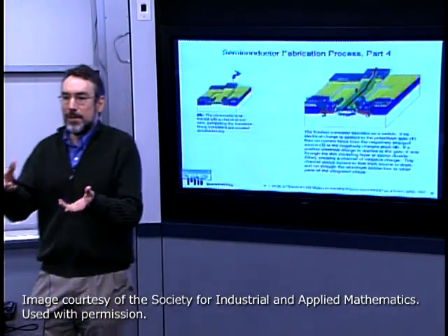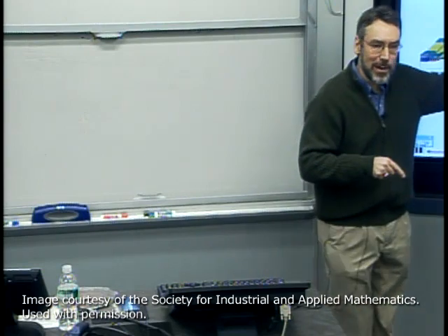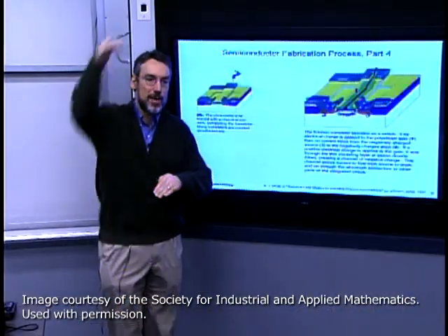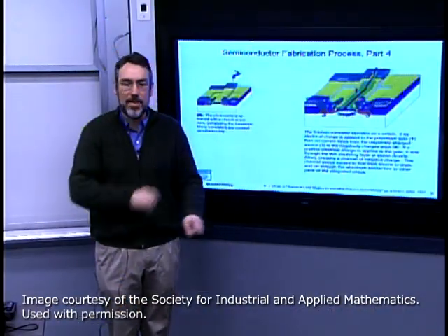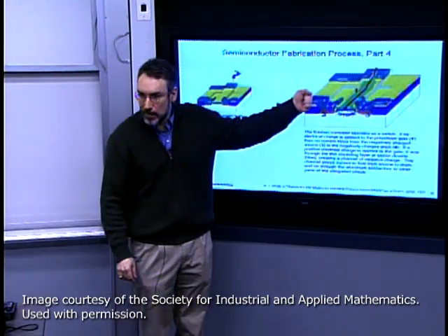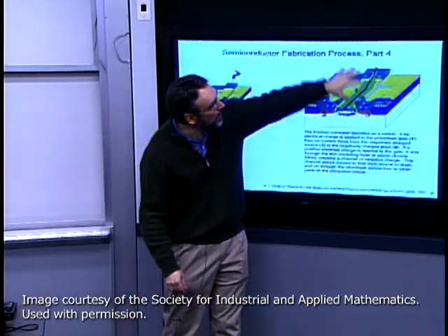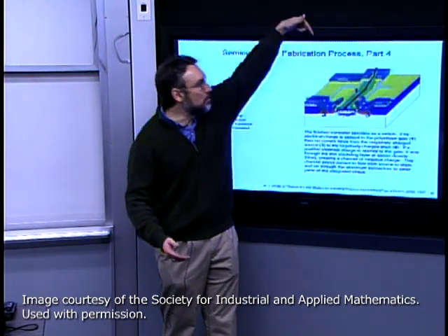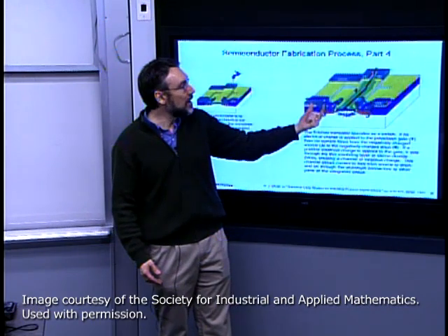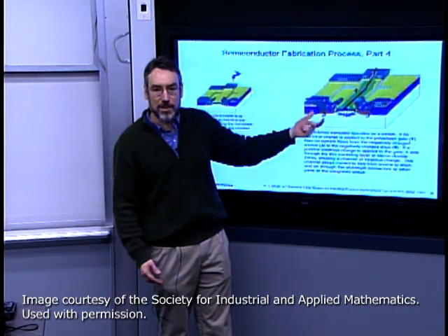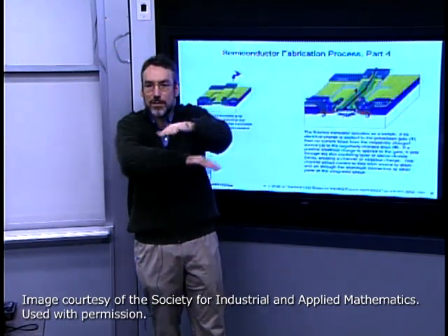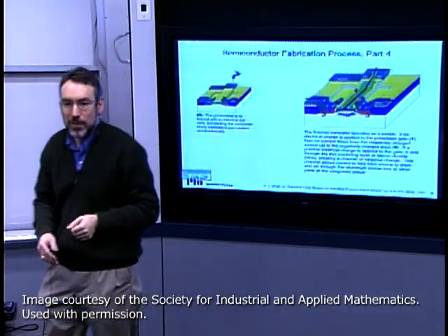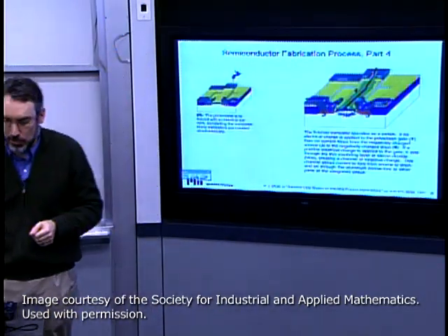When you get a certain number of transistors, it becomes very hard to have just one level of wiring. You need to be able to have a wire that goes over another wire. And that's where we get to multiple level interconnect structures, where one would deposit another layer of silicon dioxide or other insulator, and then build vertical vias down from one level to the next to contact multiple streets on level 2 with streets on level 1, and so on up to 6, 8, or even 10 levels of metal in modern structures.